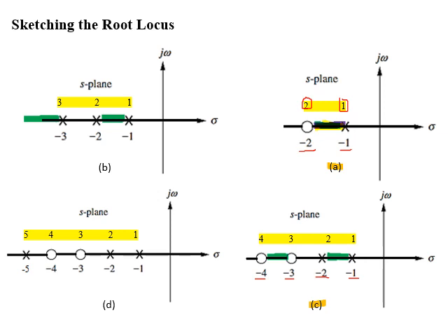Now if you look at figure D, in this we have 3 open loop system poles and 2 open loop system zeros. The root locus will exist between the pole at -1 and -2. Another branch of root locus will be between zero at -3 and zero at -4.